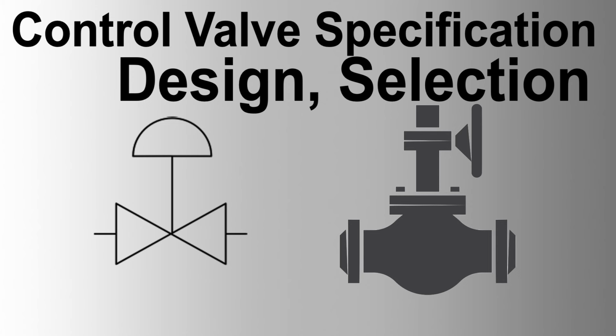6. Installation considerations. Ensure proper installation to avoid stress on the valve body, provide adequate support, and allow for easy maintenance access. Follow ISA 75.09.01 standard for control valve mechanical installation requirements. By following these detailed criteria and considerations, you can ensure the optimal selection and performance of control valves for various applications in gas, water, crude oil, and process gas systems.